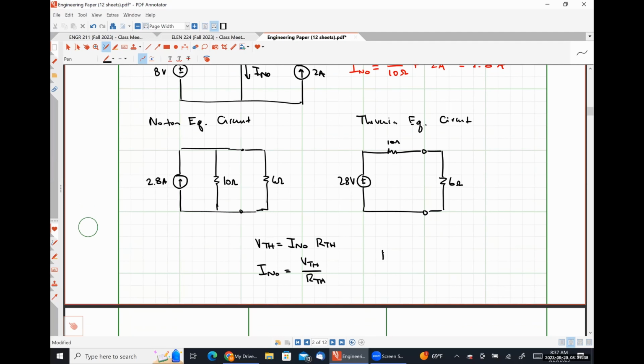We also know that the Thevenin resistance can be described as the ratio of the Thevenin voltage to the Norton current, which means we inherently have a way to check our answers here if we know how to solve for all three quantities. Or if we want to be lazy, we can solve for two and use the relationships to find out what the third one is.